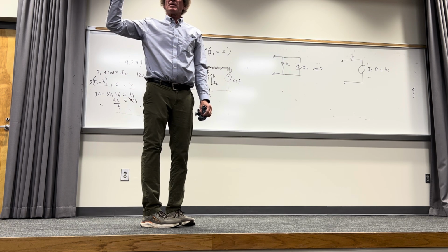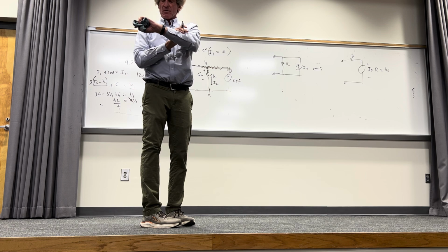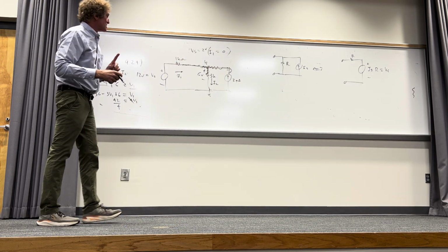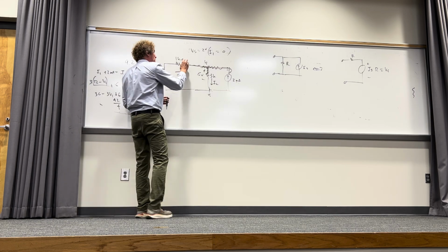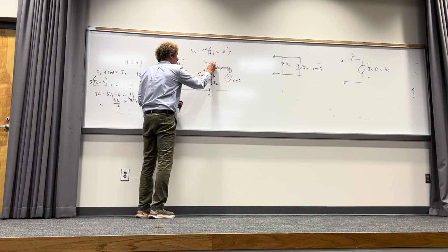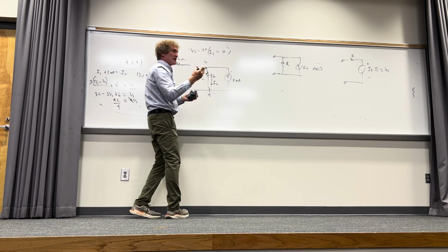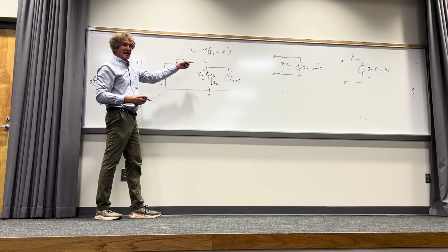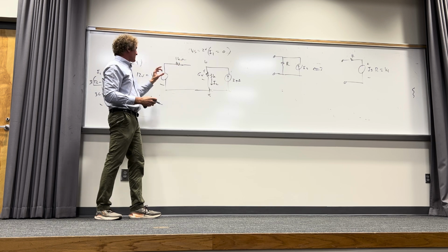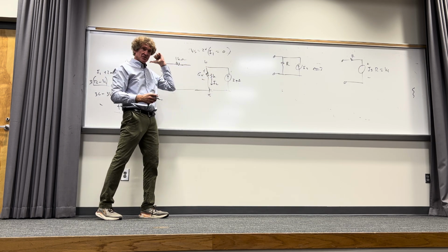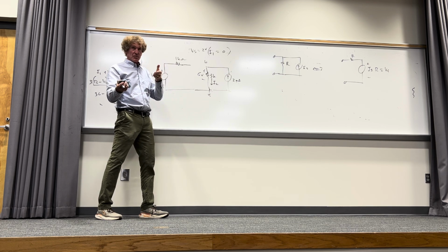Okay. What would the difference be? This is the thing I'm going for. What would the difference be if it was a non-ideal diode in this analysis? First, let me ask you this. Would the diode be on? That threshold to overcome is 0.7 volts, right? If it's 0.7 volts, I got 12 pushing it that way, and I have effectively 6 pushing it this way, right? It can be overcome. Do you agree with this?